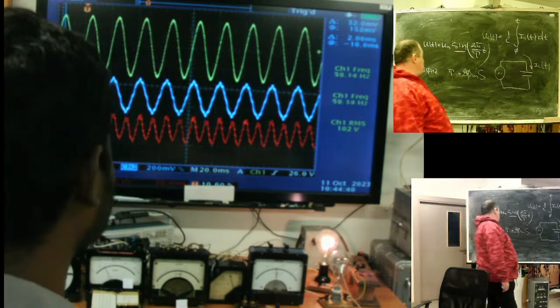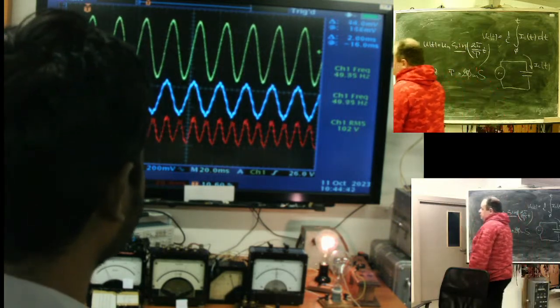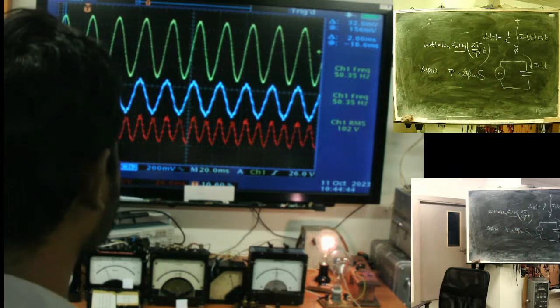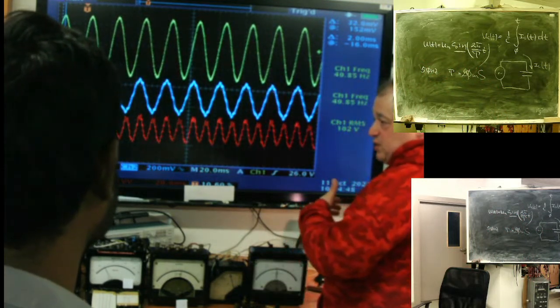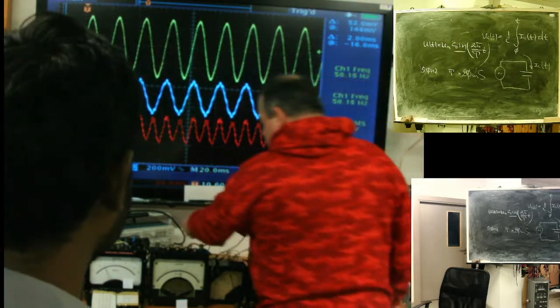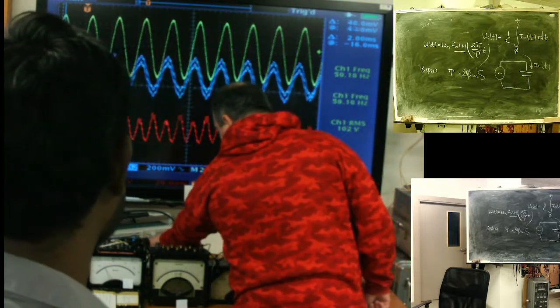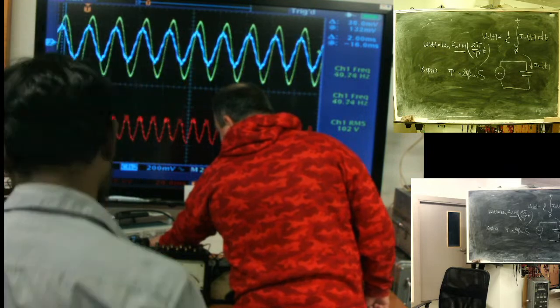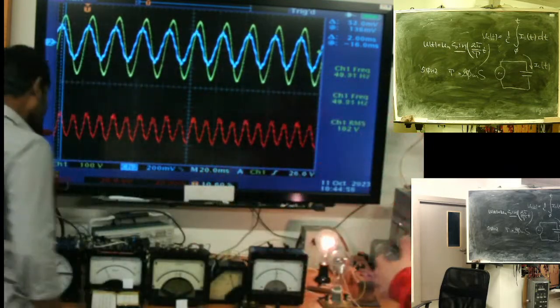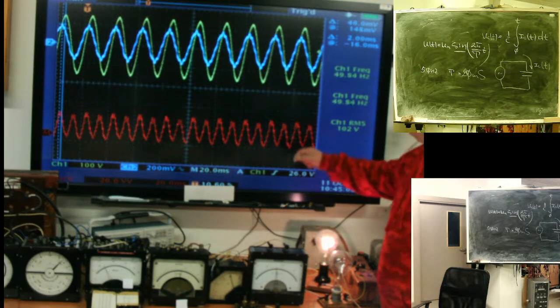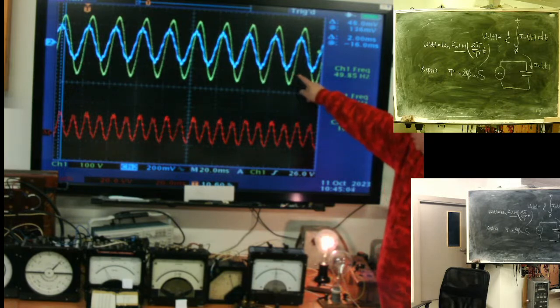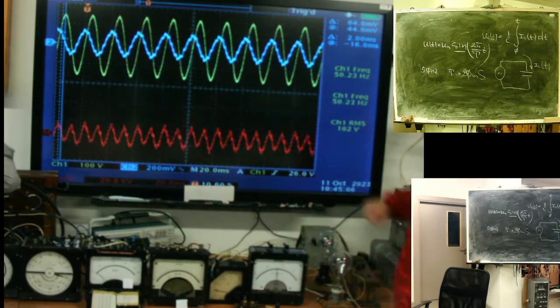In the stable regime we can see that the capacitor voltage is delayed relative to current, because the capacitor needs to charge. A capacitor has inertia. It can store energy. This means that relative to voltage, the blue line, the current, comes first. Here is the pure capacitor current.